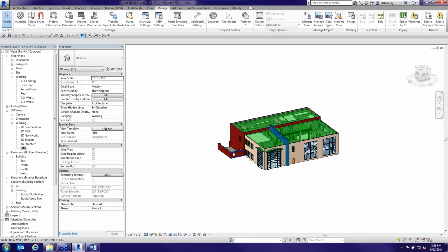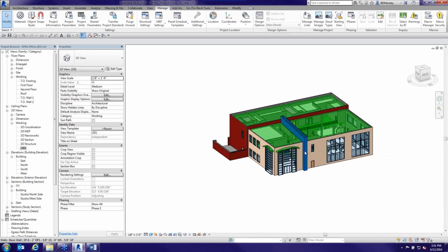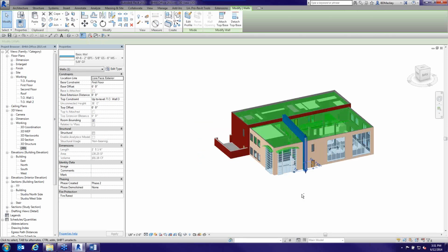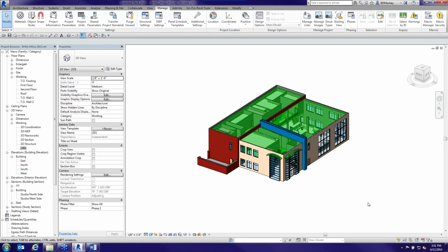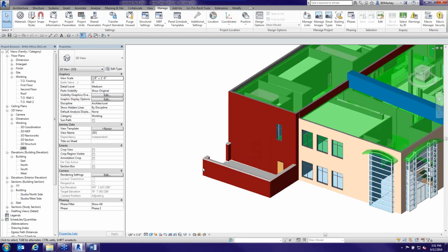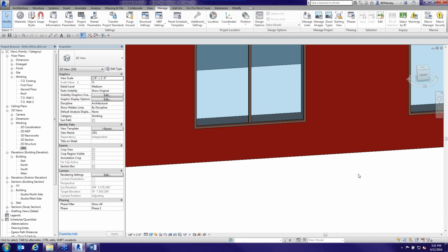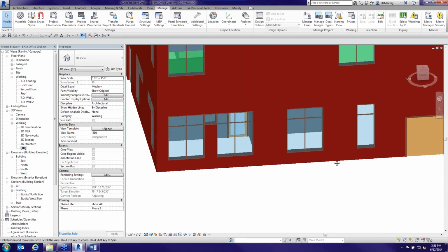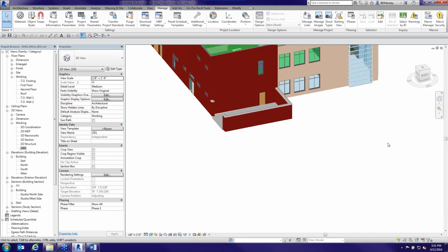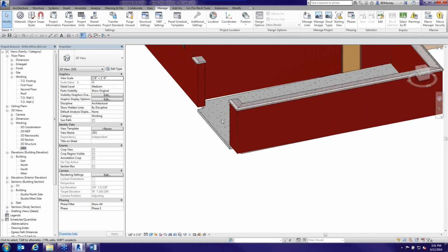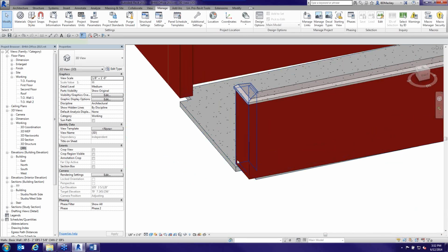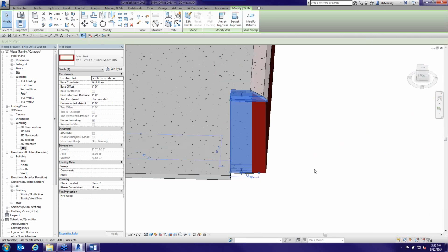It keeps that until you reopen the view, or if you pick something new as the pivot point, then it'll adjust to the new object's pivot point. That's something big to me, because a lot of times I'll be zoomed into a corner, and I want to spin, and I'm like, oh crap, where did my view go? If I just would have been zoomed into the corner and picked something first, see, now I'm going crazy and you guys are getting seasick over there. If I would have picked something in that corner first and then pivoted, the center of that object becomes my pivot.